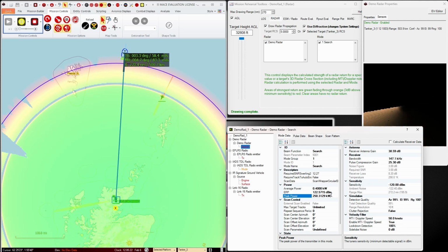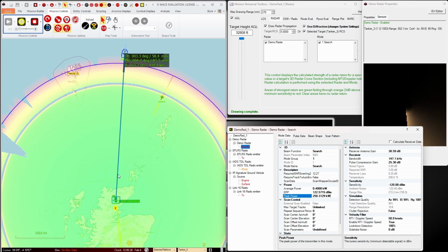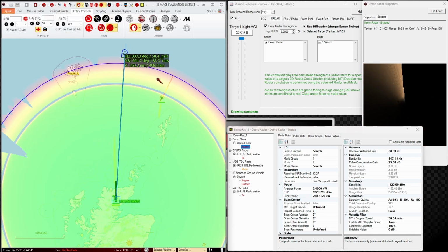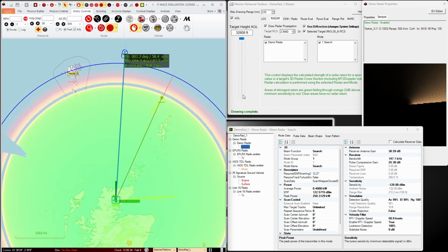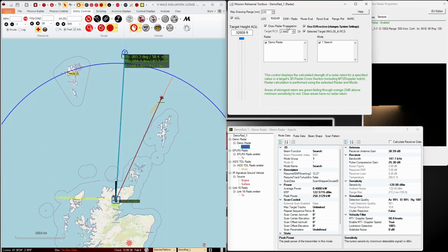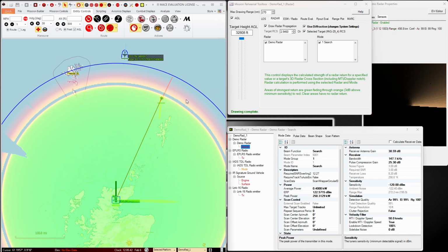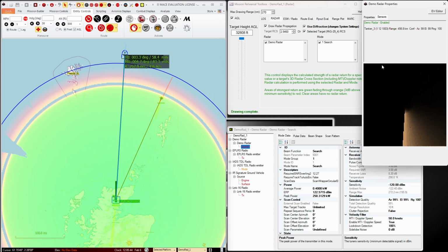Once we've done that with the simple generic tanker entity that only has the single figure for its radar cross-section, we can just target the more complex fighter platform with its 3D radar cross-section and see how the plot looks for that as we turn the aircraft in different directions and its radar cross-section that is actually seen by the beam that's hitting it changes in relation to its aspect.